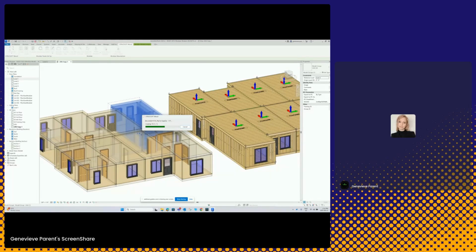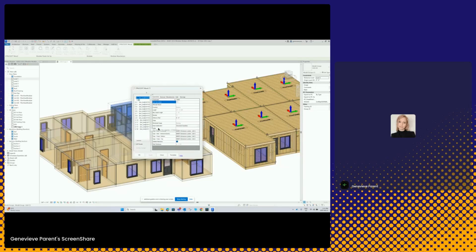So it is taking a minute, and I do believe it's going through all the walls, but this is the thing, and this is kind of the catch where I wanted to show you guys, is that if you do use the create on the entire module, you're only selecting one template for the entire series of walls. So that's something to be mindful of. You might want to just tab select one wall at a time and just use the create in that way. So this definitely won't be applying the way a template map would.